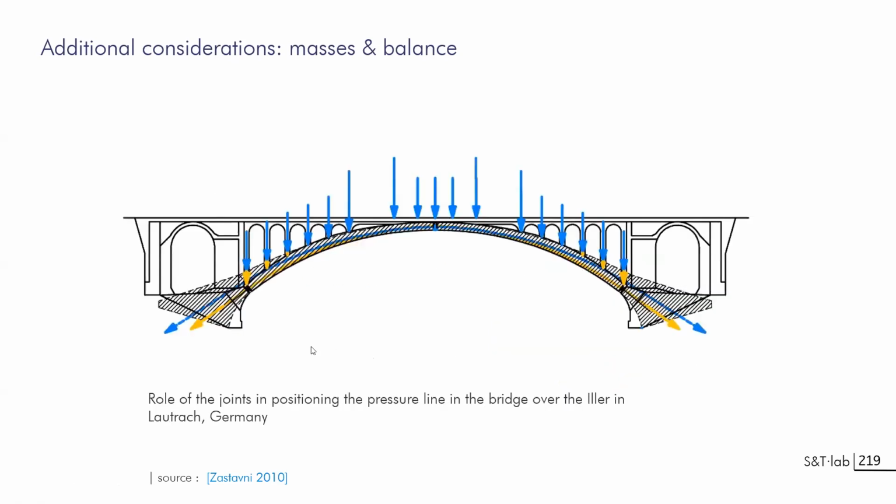If you are drawing an arch that has a certain thickness, you can have a thrust line that is running anywhere in the system and you cannot decide. But as soon as you develop a specific device with hinges in the arch, one central hinge and two side hinges, you have to draw the thrust line passing through these hinges, and this will decide where the line of action will have to pass on both sides and in the middle. This can be explained since the thrust line is a pressure, a direction of forces, and in hinges you cannot sustain bending forces. So you cannot have a distance between the hinge and the trajectory of forces that would make bending appear. So it shows that a thrust line has to pass through these two supports.